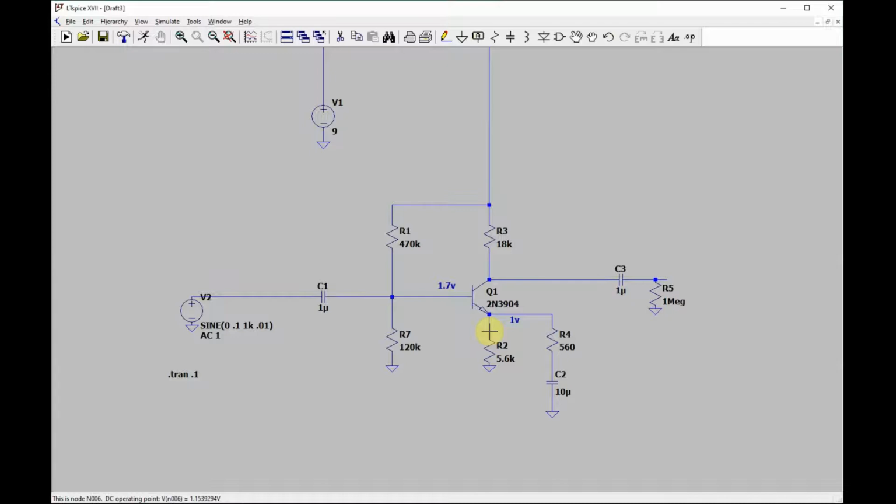A lot of times you've got to look at the design, but if you've got some good impedance matching here, and you start to lower it and lose some signal, you have to ask yourself the question: yes, I'm losing signal from the impedance mismatch, but I'm also amplifying it more from here. And usually amplifying it typically wins. You usually amplify it more than the impedance you're losing. But if you get too low, it can just affect things negatively. So this is the first trick you can use.